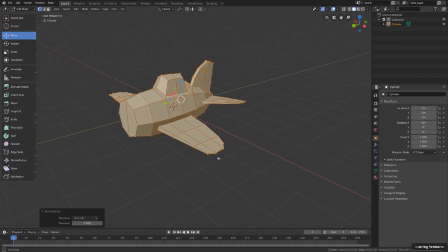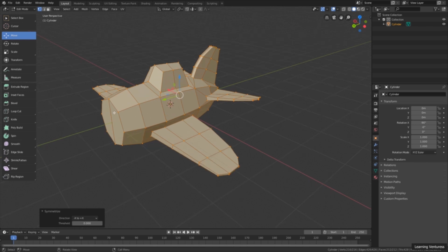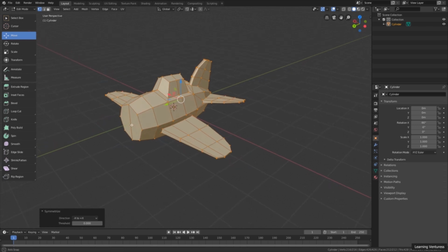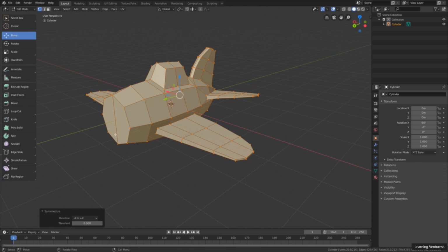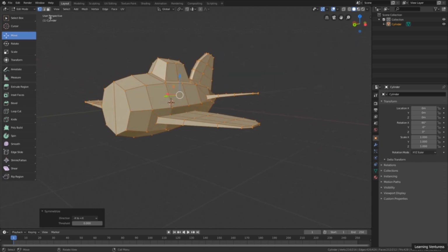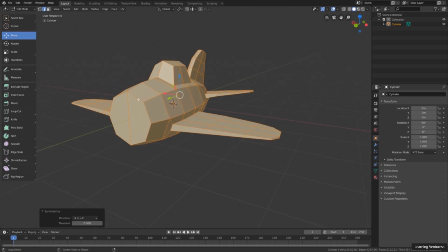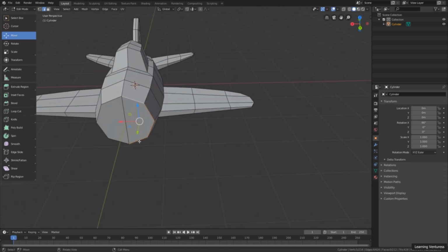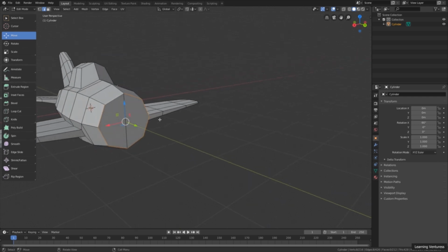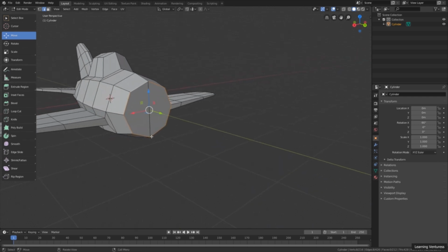And now, to finalize this lesson, I'm going to create a chamfer and a hole here in the front of the airplane so that we can add in another lesson the helix of the airplane here in the front. Okay? So I will start by creating a chamfer in this front part, and for this I will activate the edge selection mode and select this loop here with the Alt key, and with the Shift key pressed, I will need to click on the other side to select the complete loop. And I needed to do this because I have this edge here in the center.